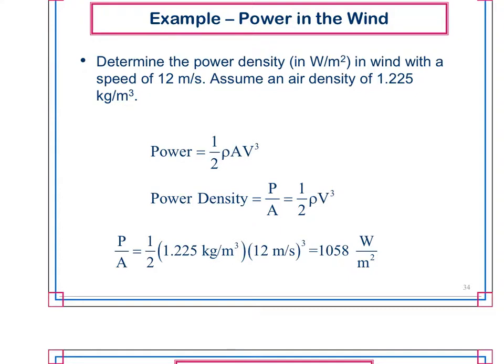A lot of it has to do with something called the tip speed ratio, and so we'll look at that in the next lecture, I believe, where we actually cover tip speed ratio. But there are some applications with very high wind speeds where it's better to go with double blades or single blades. Anything more than 3 blades tends to be for low-speed applications. So if you're running a mill or something like that in the middle of Texas with really low wind speeds, you need a lot of blades to be able to do it. So that would be a case where you would want to look more at that. We'll talk more about that when we look at tip speed ratio, but that will be more in the next video. But that's a very good question. Great question.